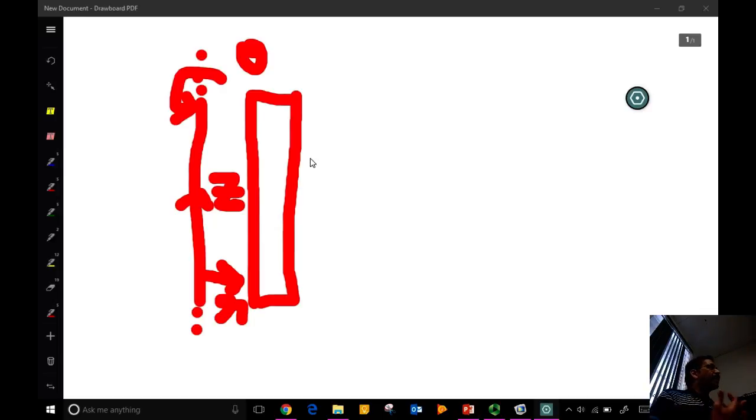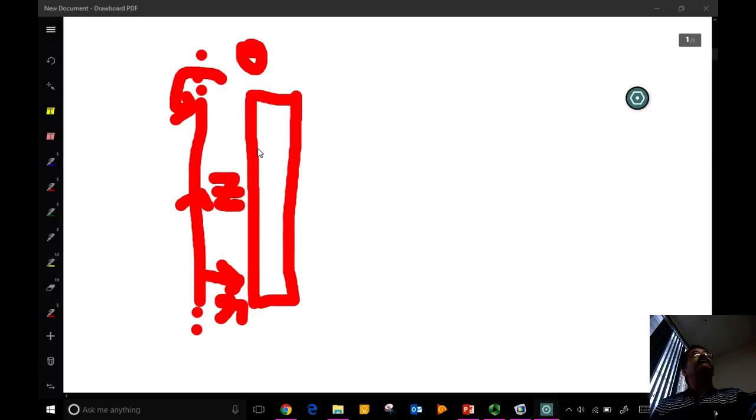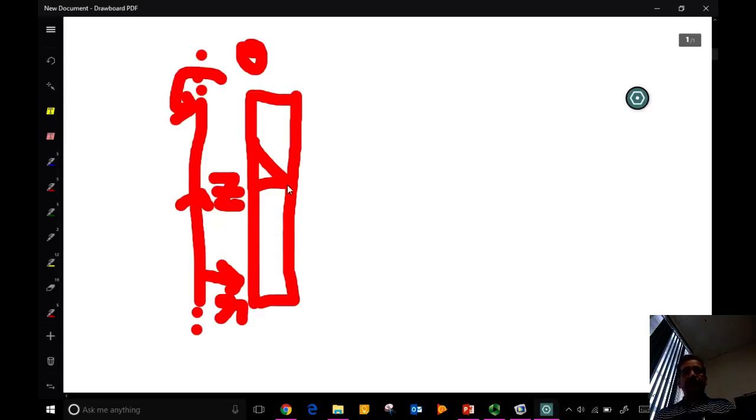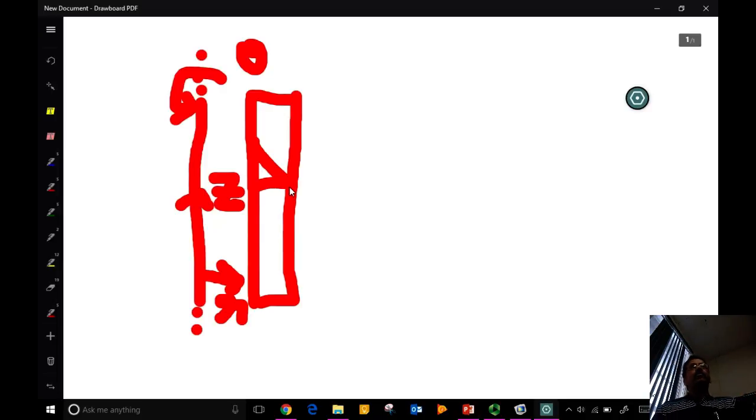But you need to make sure that the velocity field inside for viscometric measurement is linear. The velocity profile should be something like this: the inner cylinder rotates at r omega, so the velocity at the inner cylinder is r omega, the velocity at the outer cylinder is 0 because it is fixed, and in between the velocity is a linear profile. If you operate in that domain, you get a simple relationship between shear stress and shear rate.